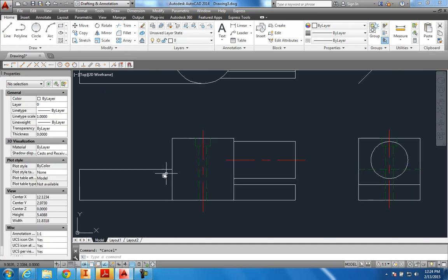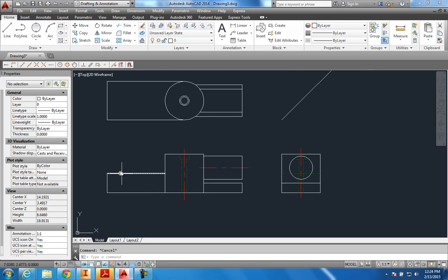So down here, is there anything wrong with this? Yes, there is. I'm showing in this drawing that this line stops right here, and that's wrong. If I stopped right here, that would make my line stop at just the quadrant of that circle. This line goes all the way up to the quadrant, so it would go all the way up to the center of this round cylinder.